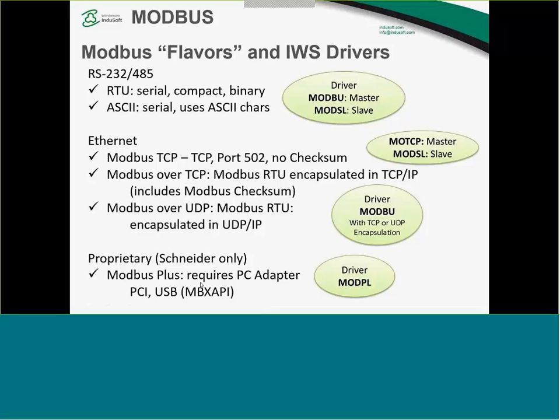Nowadays, people use the CyberLogic APIs to communicate with USB adapters from USB to Modbus Plus. For that, we have the driver called MODPL, which uses an API called MBX API from CyberLogic. These are some of the flavors that we have to use InduSoft drivers on Modbus networks.